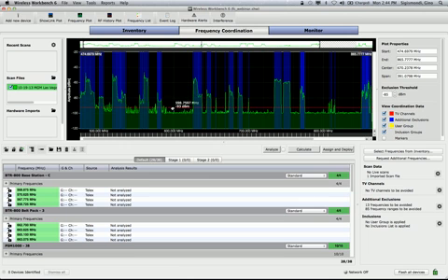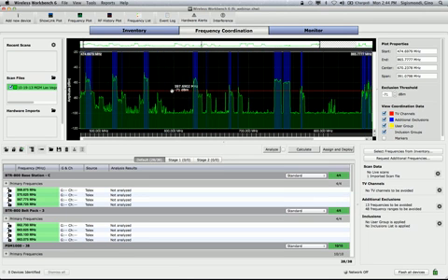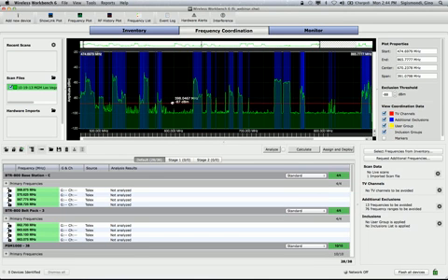And you've got full flexibility to move this line up and down depending on your need for more spectrum to use or your need for cleaner spectrum to use. So the flexibility is really in the user's hands to tailor this, but it's extremely quick to get data up and to get exclusions up and running to avoid noisy spectrum. So thanks to a friend, this data came from the MGM in Las Vegas. Wouldn't want to be running wireless there myself, but it's got to happen all the time.